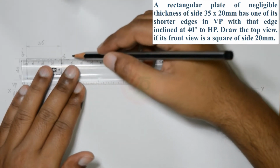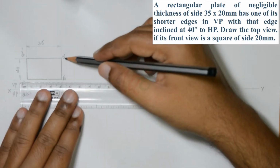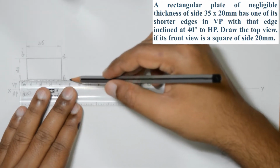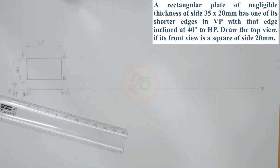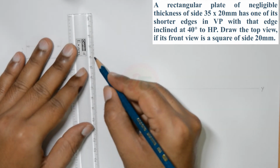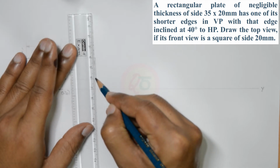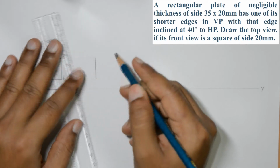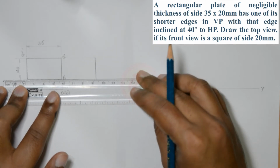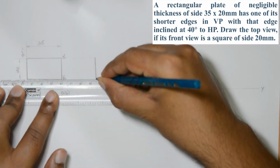Since the distance from A dash to B dash is 20, let's take the projections from A dash and B dash, sufficiently away from the first position, and construct a square of 20 mm, marking the front view in the second position as a square. So this is a square of 20 mm.